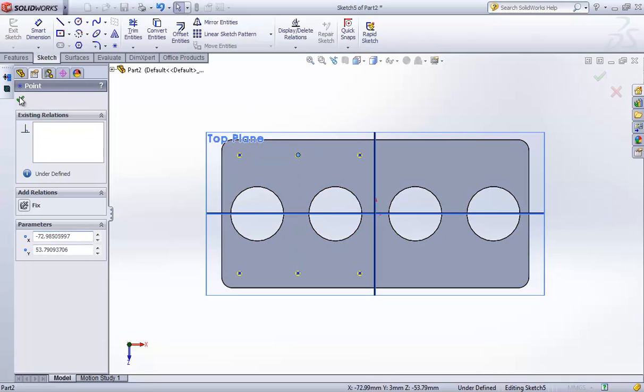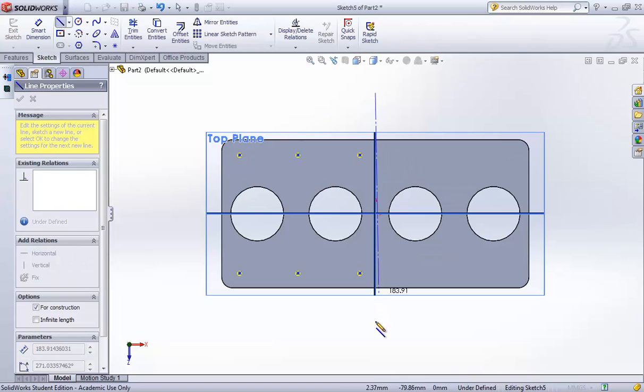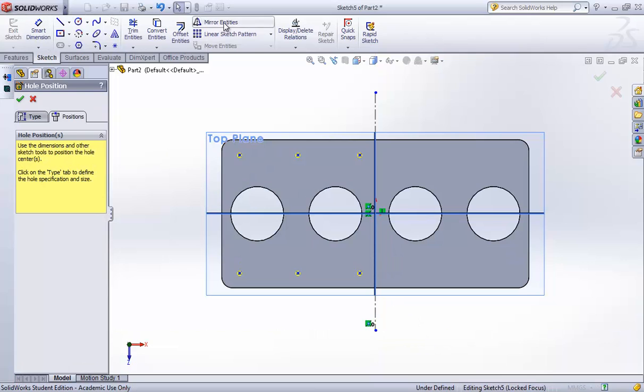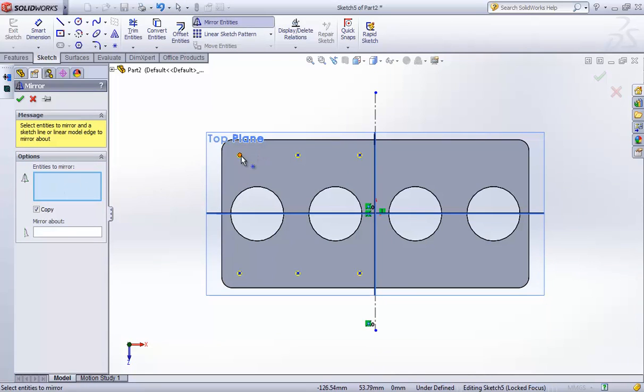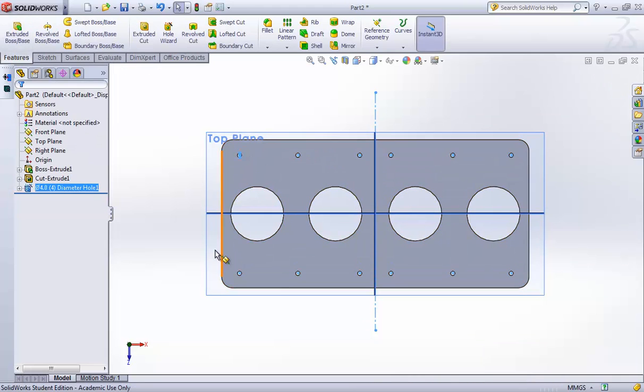Right, once again I can use construction line as mirror. So if I can select all of these small little circles I created earlier, or small little points, I can use the construction line as the mirror, and we should have it. It has got a nice nicely arranged symmetrical relationship, so on and so forth. Obviously that distance doesn't look really large, so I'll let you guys deal with that. And there we have it.